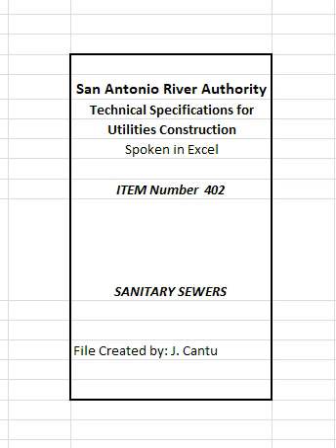All sanitary sewer mains shall be constructed in accordance with the specifications herein outlined and in conformity with the required lines, grades, and details shown on the plans and as directed by the owner engineer. Successful passage of the air test as described under item number 518, air testing, shall be required for the acceptance of the mains. The requirements of item number 527, television inspection, shall be met before acceptance of the line.